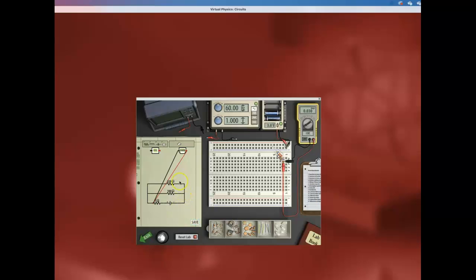Now we are going to do the voltage measurements. Now I want you to know that we should remove the 1 ohm. Don't leave it here. The 1 ohm should be removed from the circuit before measuring the voltage. If you keep it, then this is going to be a mistake. Now I will have it as a voltmeter.